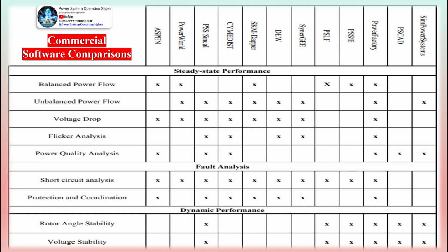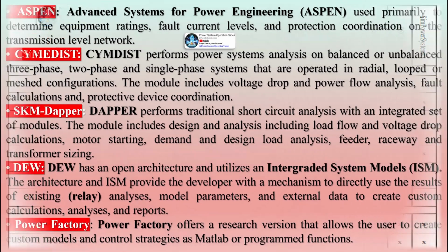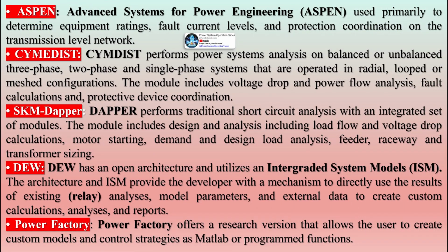The question is, what is short-circuit analysis? A short-circuit analysis essentially consists of determining the steady-state solution of a linear network with balanced three-phase excitation. Such an analysis provides currents and voltages in a power system during the faulted condition. This information is needed to determine the required interrupting capacity of the circuit breakers and to design a proper relaying system.